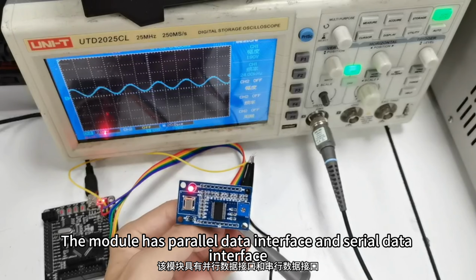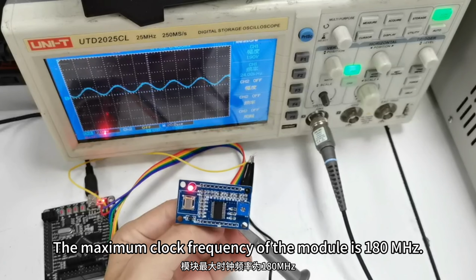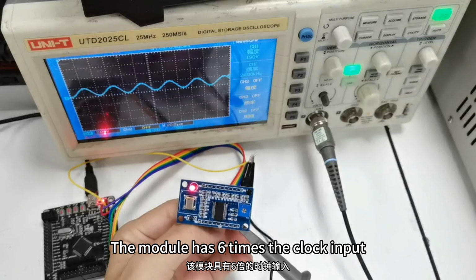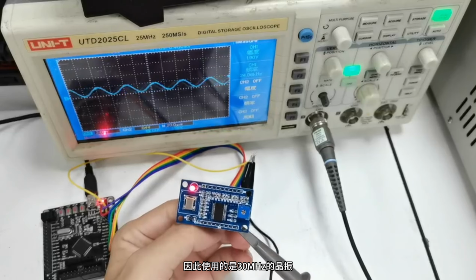The module has a parallel data interface and a serial data interface. The maximum clock frequency of the module is 180 MHz. The module has a 6 times clock input, so a 30 MHz crystal oscillator is used.